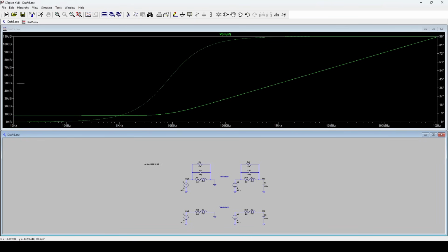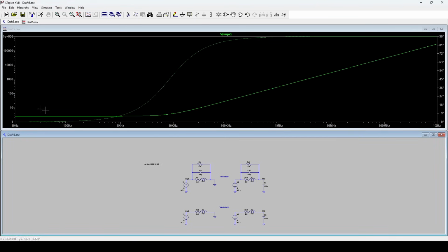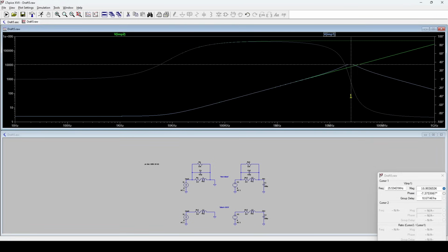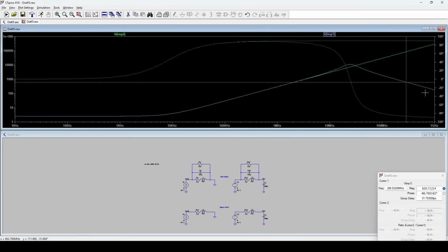And this is exactly what we expect. I'll change the graph to magnitude. On the left-hand side, at DC, we get our DC resistance. We get this somewhat flat band up to a corner frequency, and then our inductive region to infinity. If we plot our more non-ideal impedance, in addition, we can see we get the same low-frequency performance, we get the same inductive performance up to or close to our self-resonant frequency, after which these models differ quite considerably. Our non-ideal model has our self-resonant frequency as we calculated at around 24 megahertz with a magnitude of about 11 kilo ohms due to this parallel resistance, after which this winding capacitance dominates and we get a reduction in impedance magnitude.